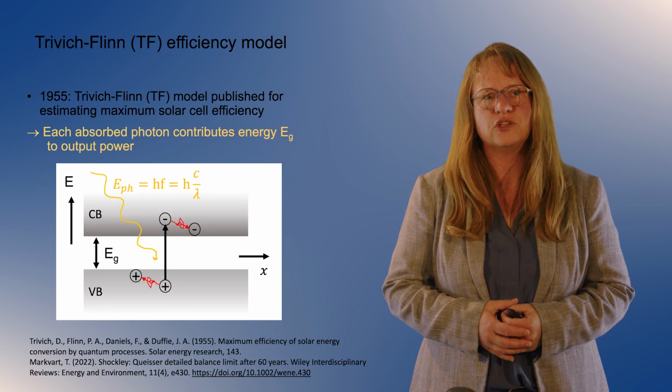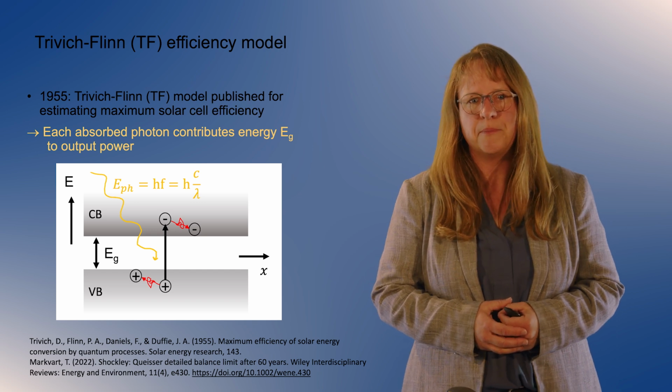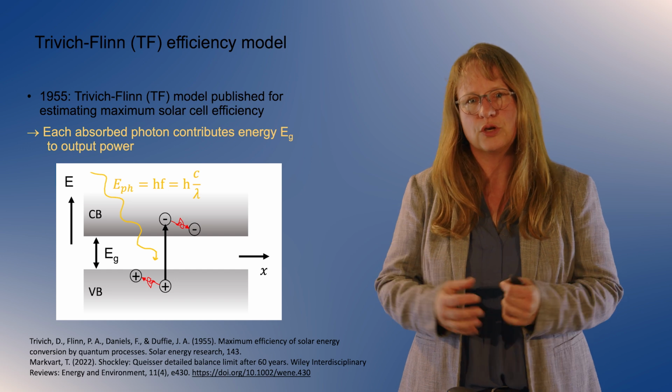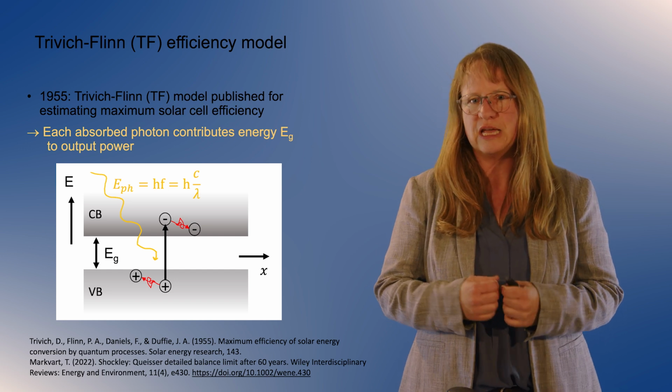Hello, and welcome to this video. In this video, I'm going to show you a first model of how to calculate what the maximum efficiency is for a solar cell of a certain band gap. This model is the so-called Trivich-Flinn efficiency model that was published in 1955. We are going to consider this model, first of all, to estimate how much energy we can extract from